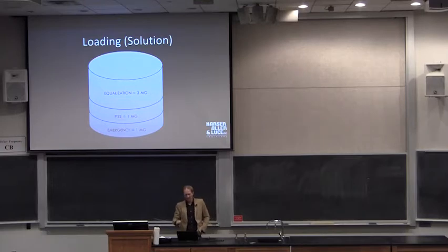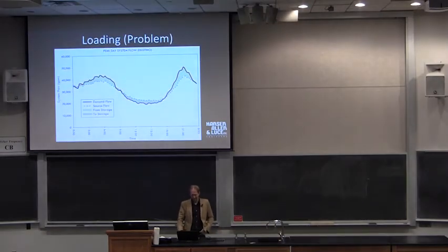Now most operators, they'll keep the tank completely full because that's their job, is to keep water in the system. And that's the last thing you want to see, their tank going empty. So because of that, they try to keep their tank completely full, and they don't take advantage of the equalization storage, or in other words, the battery.